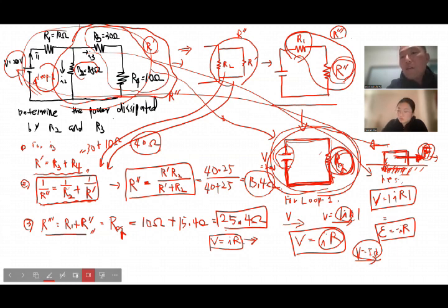Ideally, that's when the current comes back to the battery and brings it up to the current level which is provided to the resistor. But if the battery itself has an internal loss R, as time goes that continuously lowers the potential because it produces additional energy loss. So that's a little bit different situation than the ideal case I showed you.